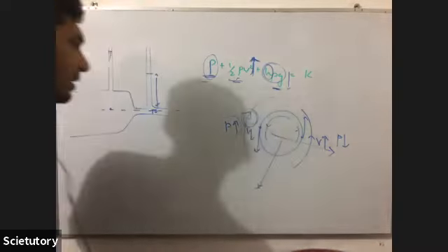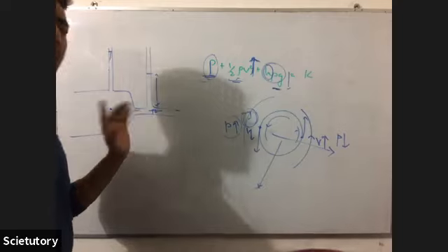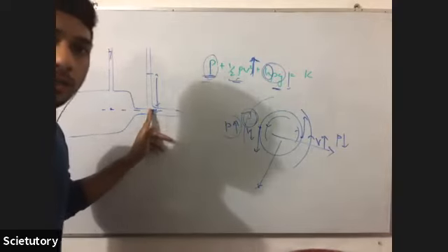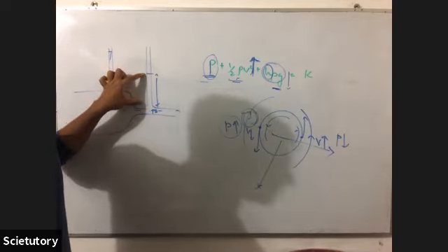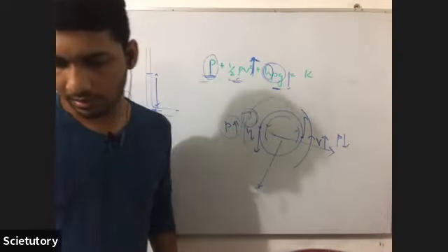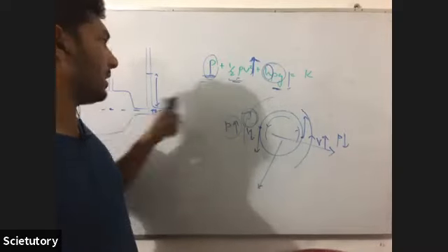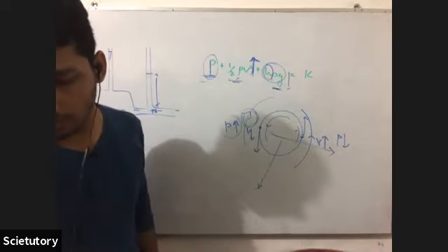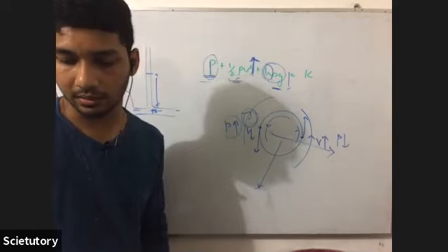Now listen to me carefully. Here the area of cross-section is higher, so velocity is lower. Here the area of cross-section is lower, so the velocity is higher. So the pressure is low, so the height is low. Here the pressure is high, the height is high. So it's explainable using what? Bernoulli's equation. When the velocity increases, the pressure decreases. Here the h rho g remains the same. So C and D are explained using Bernoulli's theorem. So C and D only are correct.